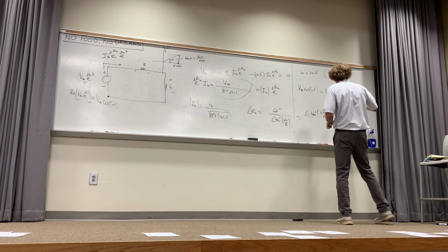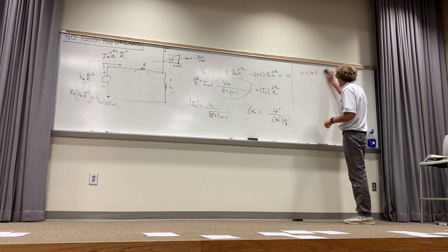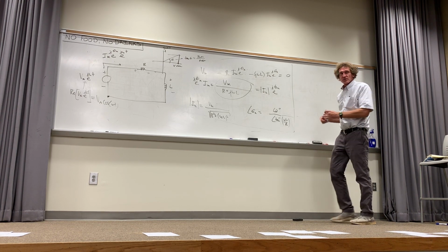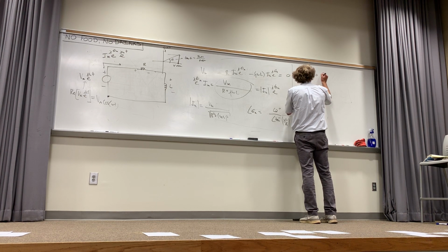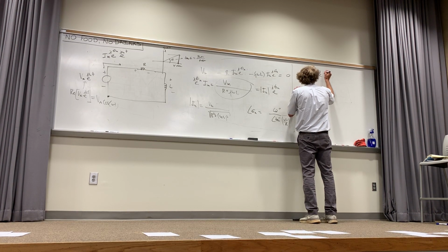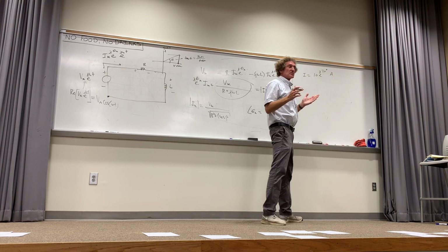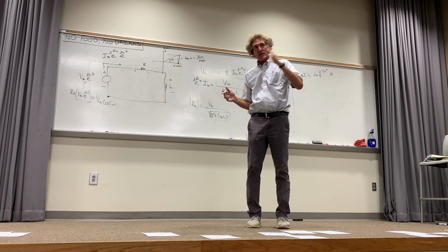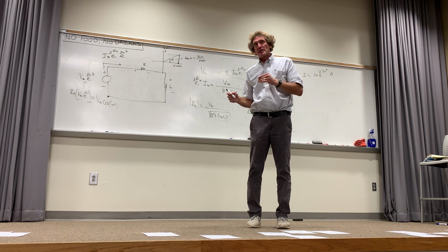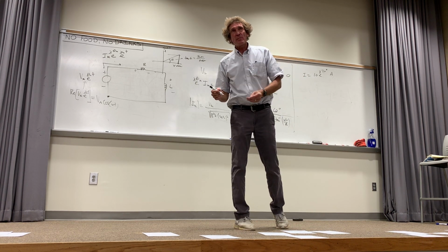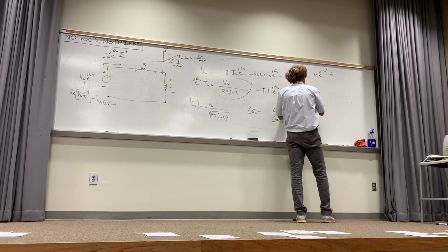Please just watch this. Some of you will feel uncomfortable with this for a little bit, but watch this. I'm going to assume for a second that I have a current I equal to 10 e^(j30°) amps. There's no jω in there. That's an angle and a magnitude. Follow me? I'm just assuming this to help you see. Now suppose I wanted the actual time domain form of this. What is really there that's measurable? The way you get it is this.